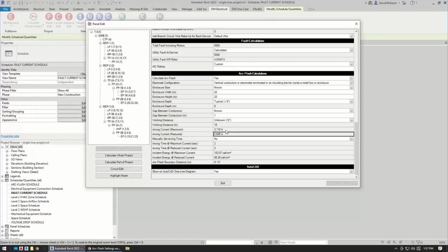So you've got the two currents that they recommend: figure out the trip time for these two arcing currents. These are what you take to your breaker curve to figure out your arcing time. We'll look at breaker curves in just a moment once we've finished this out here.